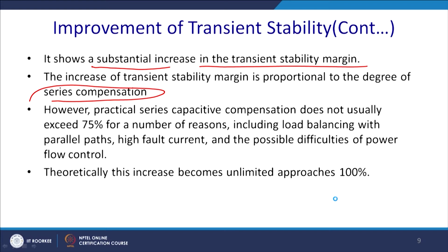However, there is a practical issue, because the current will be so high. So, the practical capacitive compensation does not usually exceed 75%.